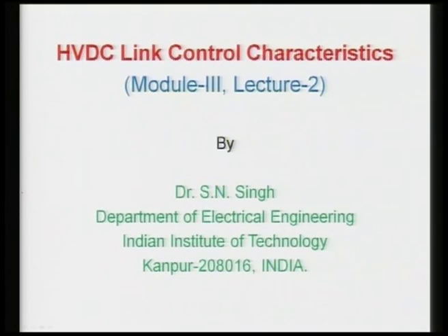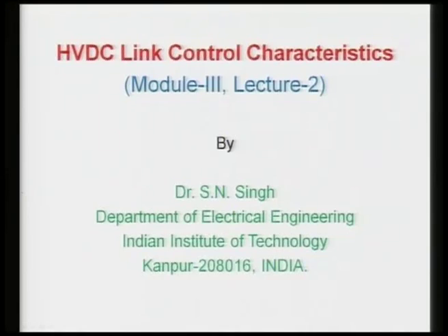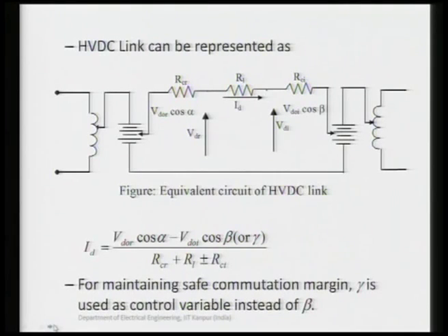Let us start lecture number 2 of this module 3. Today I will discuss the HVDC link control characteristic, both rectifier side as well as inverter side. In the previous lecture we saw this equivalent electrical circuit of HVDC link where we have your rectifier end and